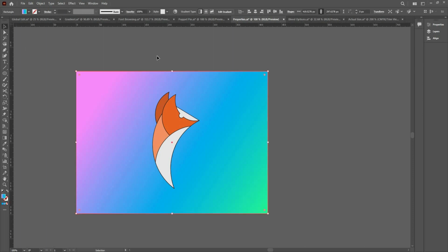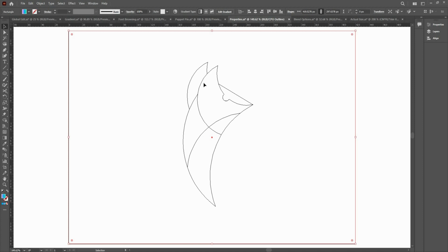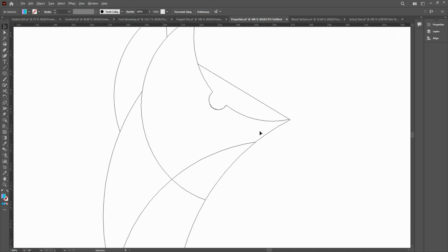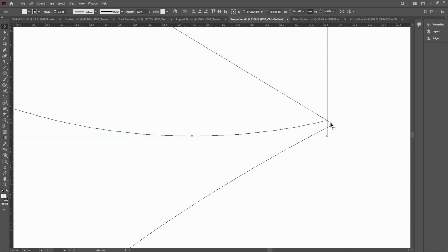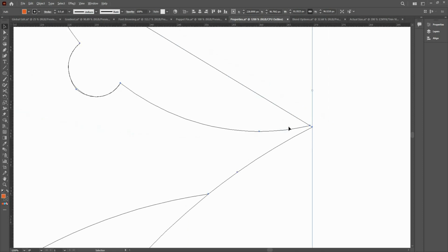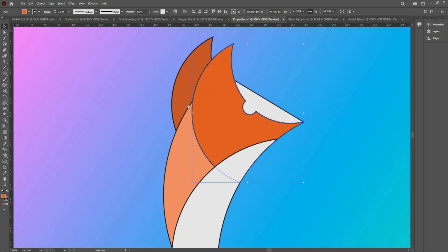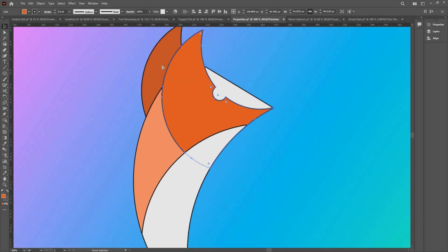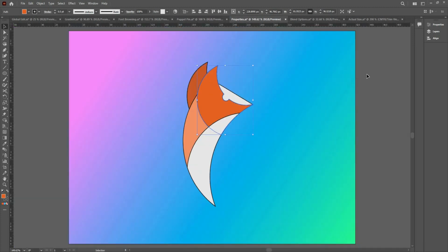And one more feature that we can discuss is the Control Y option, that is the outline mode. While drawing, if you want things to be overlapping each other properly, you can use this mode and properly align things in case the stroke is getting in the way. So you can always switch to outline mode, Control Y is the shortcut, and make your sketches properly align with the stroke. And that's about it with the additional features.